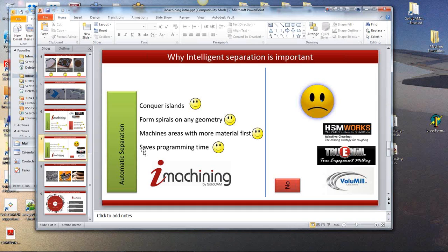But on a 3D part especially, you'll use your maximum length of flute length that it can when it's removing the material. But then when it's machining closer to form, when it's stepping up, traditionally you would step down at a certain depth, but because iMachining works backwards, it does the depth first, then it'll step up. So it uses the maximum depth of cut before it has to use the smaller depth of cut. So I call them step ups.